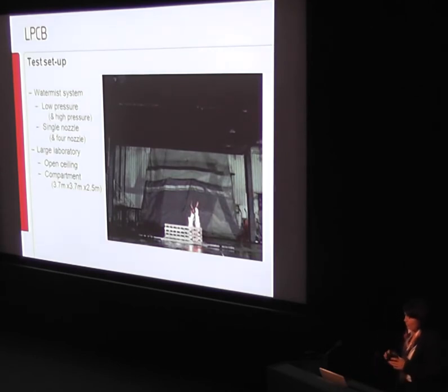So what we've tried to do is, as I said, there's a lot of work being done with flammable liquid fires, and we were wanting to look at the Class A fire, the area that we perceive to be more difficult for water mist. We looked at low pressure systems and high pressure systems, but mainly low pressure, because that's generally what might be considered to be used in Class A fires, Class A being solid combustibles, if you don't know. And a lot of the work was done with single nozzles, although some 4 nozzle testing was undertaken.